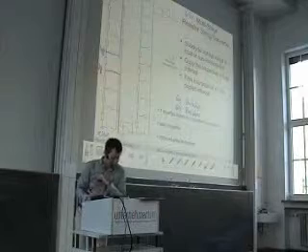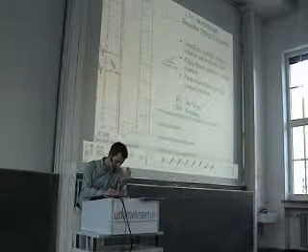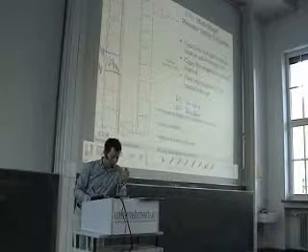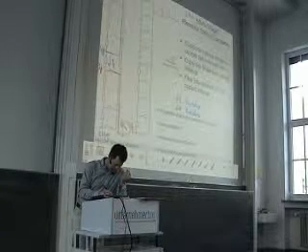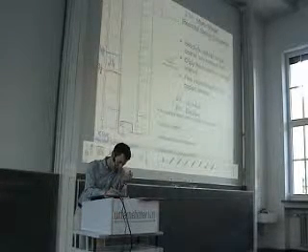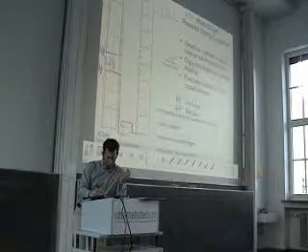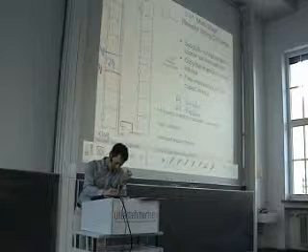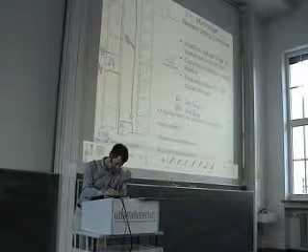So now we have taken 2 neighboring voltages of this resistor string. So the difference here is 1/8. Next step is that we use buffers to copy this voltage, and the second buffer to copy the second voltage. So we have now a copy of these two voltages, which leads to a voltage drop between these 2 points of 1/8 times Vref.